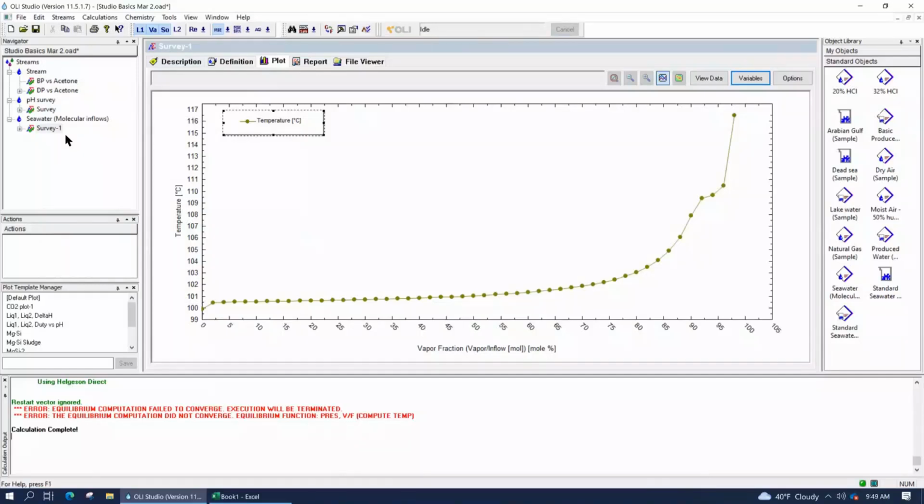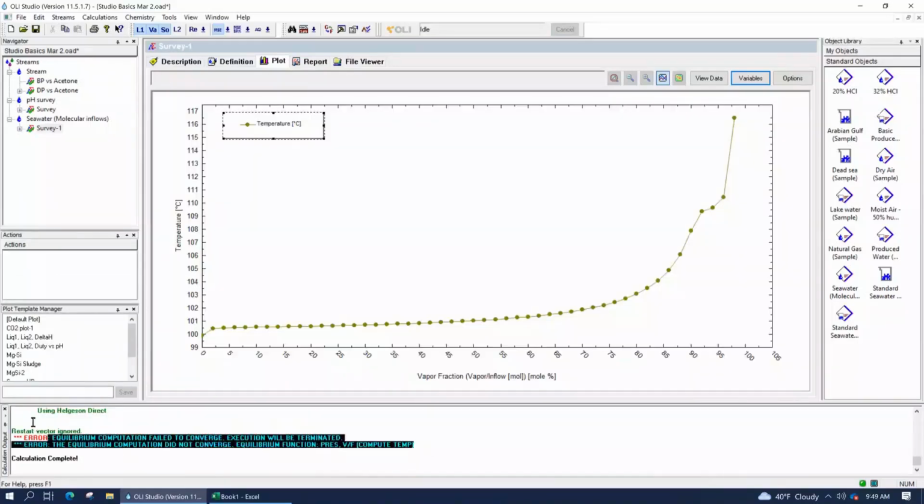So in this case, the very last calculation failed. You can see what I was describing as that hockey stick. There's a plateau here where salt starts to precipitate, but then of course it goes up even higher because you end up with what they call a bittern brine, a magnesium sulfate brine. So that's that. Always keep in mind that the software will try to achieve a global minimum on every calculation, but sometimes you give it a request that it just can't handle, simply because it's not practical. In this case, it's not thermodynamically feasible.